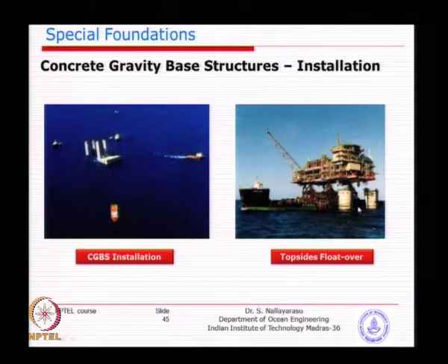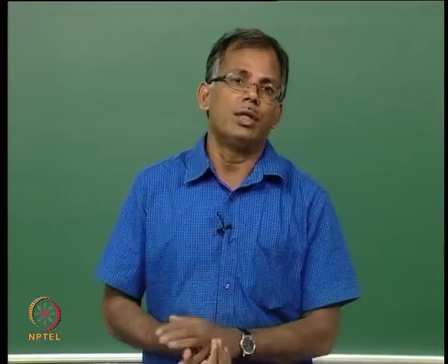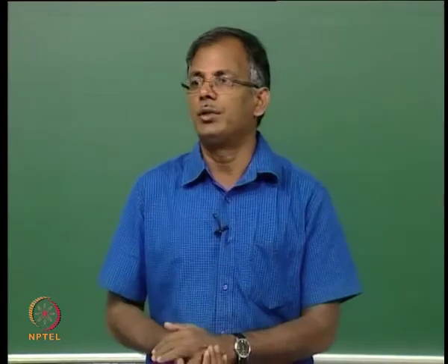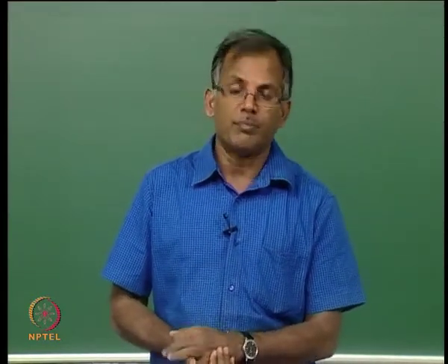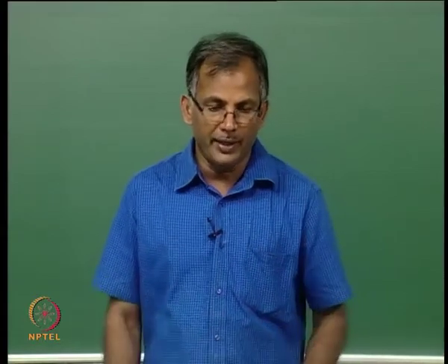When it comes to the site, you can see here the installation of the topsides. In this particular project, the installation of the topside is at the site. In some projects they have installed the topside in the yard itself, and the whole structure, with the substructure and superstructure together, is towed. Of course, the buoyancy requirement is then higher.